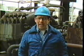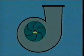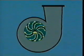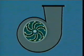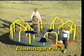Now let's take a closer look at compressor operation. When gas enters the compressor, several forces are acting on the moving gas. One of these forces is aerodynamic. An aerodynamic force is the same force that causes an airplane wing to lift as it moves through the air. This lifting force helps to move the gas from low pressure at the eye of the impeller to high pressure at the outer edge. Another of these forces is centrifugal force.